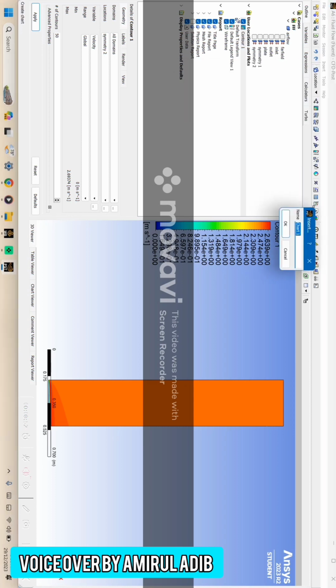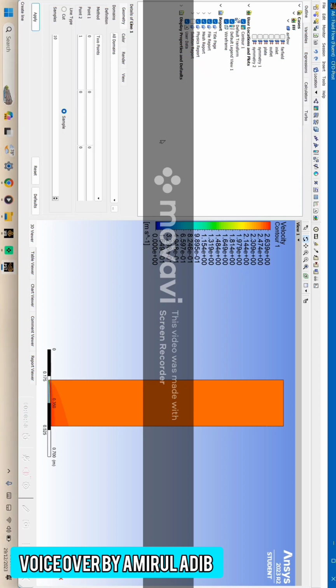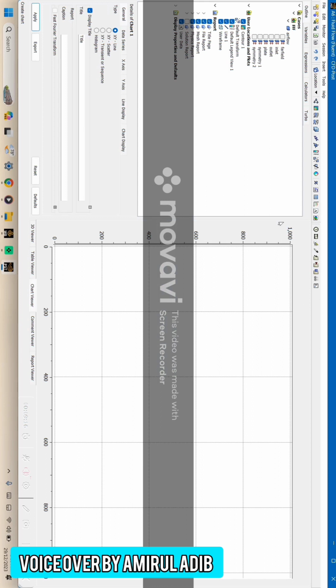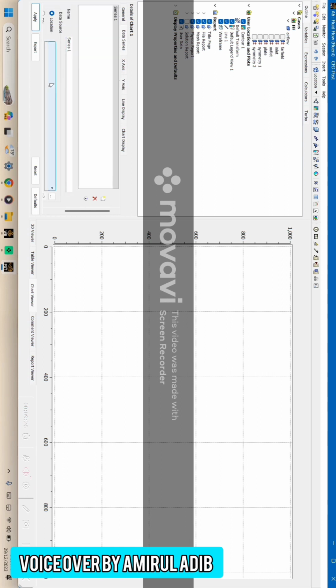For the chart, we have to build the line first. So go to location, line, and OK to insert the line. This is our length 1.5, and the end middle is 0.3. So click apply. So the line will be here. So go to chart, click OK. Go to x axis, change to velocity u. For the y axis, go to y, and for data series, click the location of line 1, and then click apply.